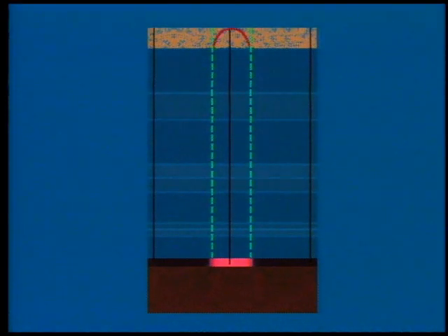However, in reality, there is not only a confining layer, but many impermeable layers above the injection zone. For migration to occur, there must be some other avenue or conduit allowing fluid movement. For example, an improperly plugged abandoned well located here within the endangering zone creates the potential conduit for salt water to migrate into an underground freshwater source.